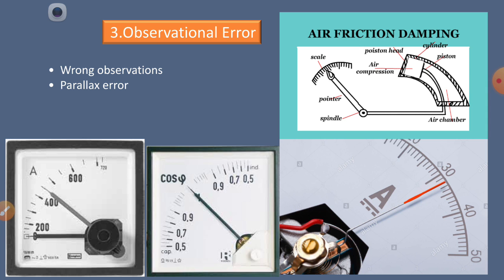And sometimes there are two arrows, a reference and another one. So instead of taking the other, you are taking the another one. In MD meters, maximum demand meters, generally installed in small industries, for the calculation of the current bill tariff there are two pointers. So you have to take the one which is the reference, the normal moving one. So these are the possible errors while observing these readings.